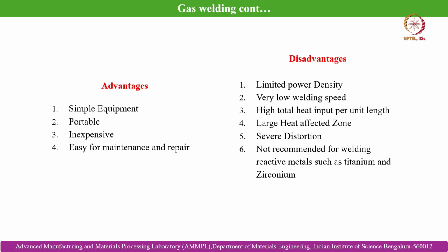It also creates a large heat affected zone in the weld joint, causes severe distortion, and is not recommended at all for reactive metals such as titanium, zirconium, magnesium, etc. It also has a very low welding speed and limited power density.